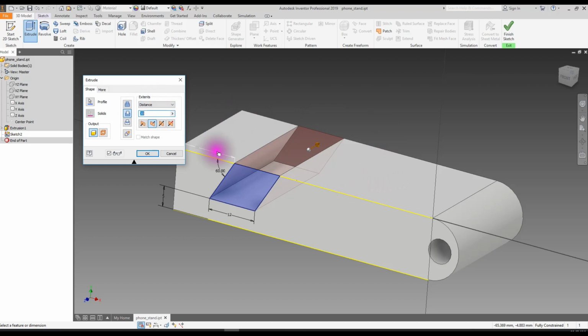But say we later go in and say we want to make this 40 wide, not 30, and you open up the first sketch you made, the first extrusion you made, and change that to 40, then suddenly your hole will only be 30 deep and it won't go all the way through. So if you say through all, it will always go through all the material, no matter if you change other features. So if you want it to go all the way through, use all.